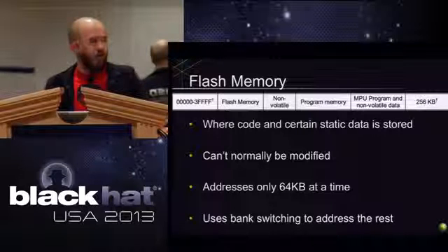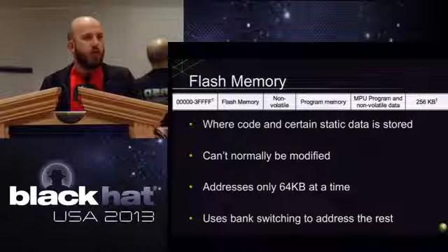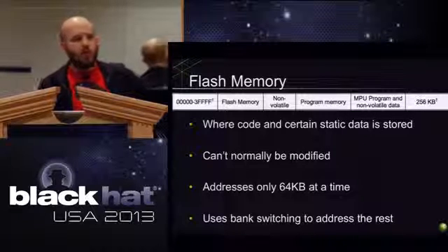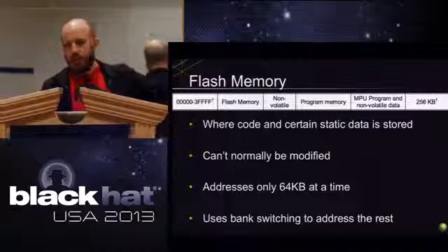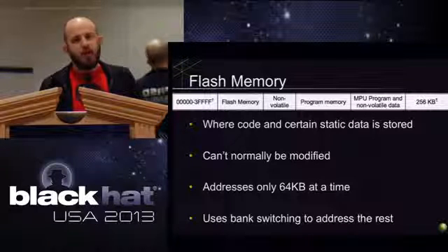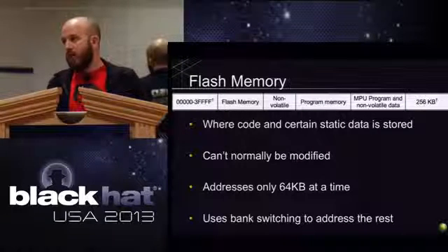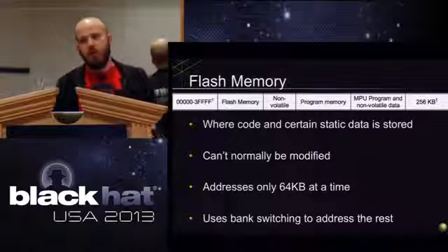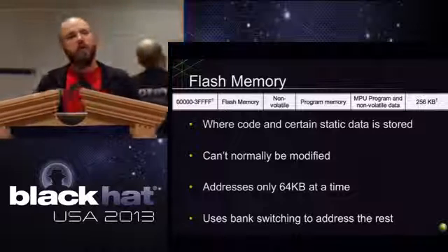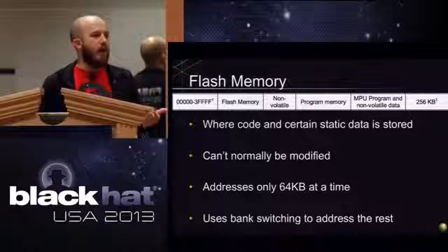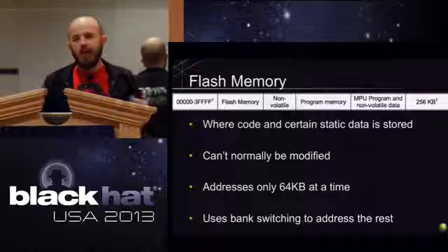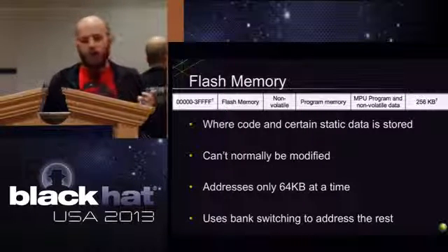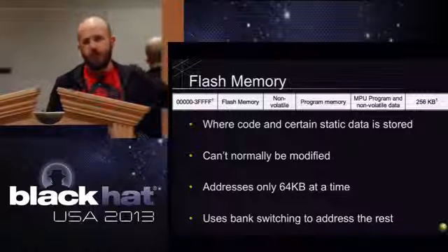Flash memory itself can't normally be modified. True Harvard would mean that this would be read-only all the time. You'd load code with a JTAG or whatever, and then you send the production device out, and then it never gets modified ever. Now the reality is that nobody can do that. Nobody can ship code on a device and then never update that code again. So what that means in the real world is that nowadays Harvard architectures require the ability to somehow modify flash memory. You've got to jump through 10 different hoops to make that occur. But the general statement is that you can't modify it.